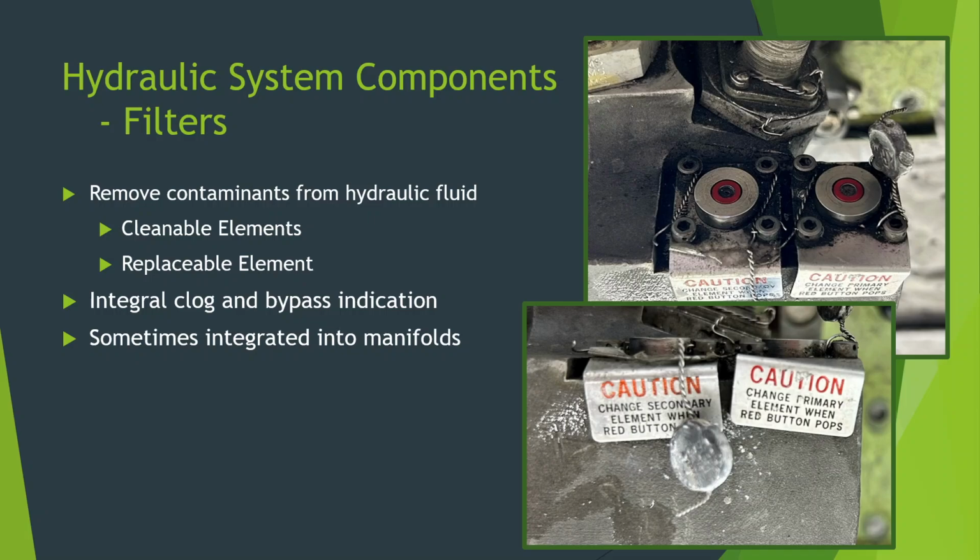And so when we did our daily checks on the aircraft, a typical transport aircraft operating in an air carrier environment has to be looked at by maintenance every 3 to 5 days. They would come in for something called a service check. During a service check, we would make sure the lights were working, check tire pressures, check engine oil levels, and we'd go around to each of the hydraulic filters and make sure that none of the impending bypass pins were popped.